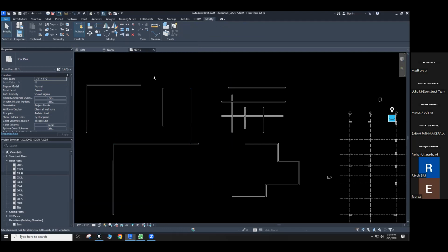Again, I repeat, see, undo, go to the single trim, single extend. But this case is extend, right? So both are the single command, don't forget. And you have to select the perpendicular object first and click the extend object to extend to the nearest perpendicular line.